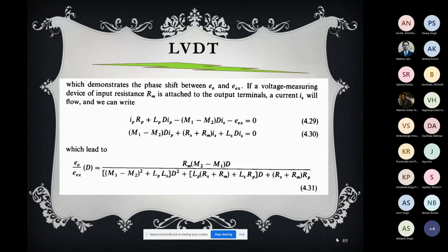At very high frequency, all the poles will contribute, so you will have two poles, so minus 180 degrees will be coming from the poles, and plus 90 is coming from the zero at origin. So at very high frequency, the resultant phase you will get is minus 90 degrees. So the phase will change from plus 90 to minus 90, and at some frequency, the phase angle will be 0.